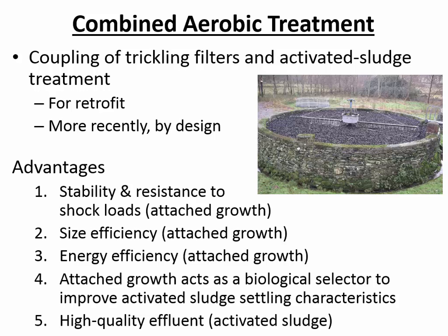The advantages of combining these two technologies together is you get the resistance to shock loads that can exist with a trickling filter. Remember, that's because the slime layer is so thick that even if the outside of the slime layer is damaged by a toxic material or a really high concentration of BOD, then the rest of the slime layer beneath that is unaffected.